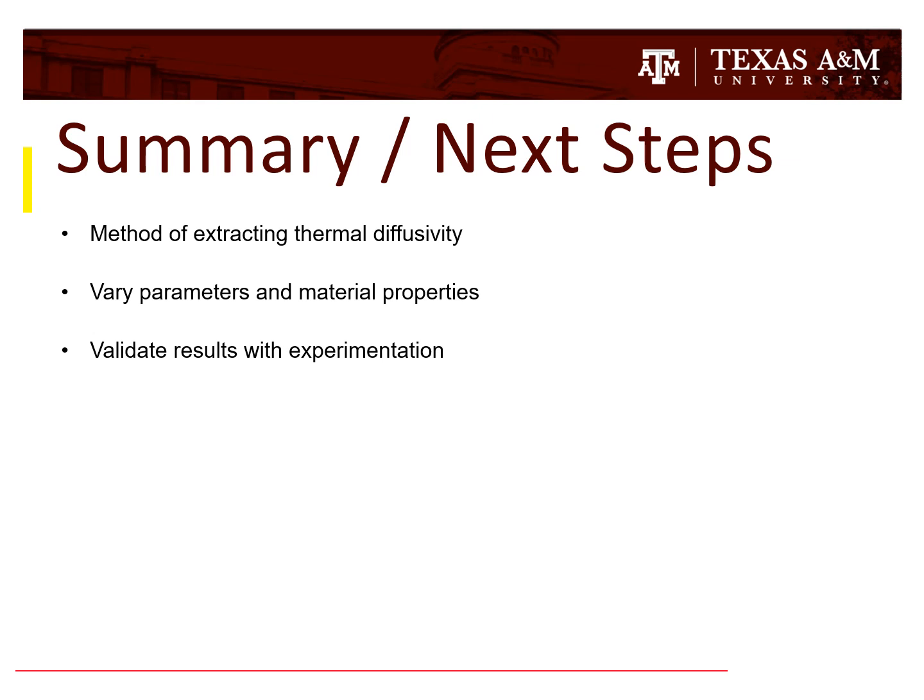We now have a method to calculate the thermal diffusivity for an unknown material during high heat flux testing by relating it to the phase lag found in the simulation. The next steps for this research include to vary the parameters and material properties to further validate our experiment, as well as validate our results with experimentation from the lab and the data gathered in real life.